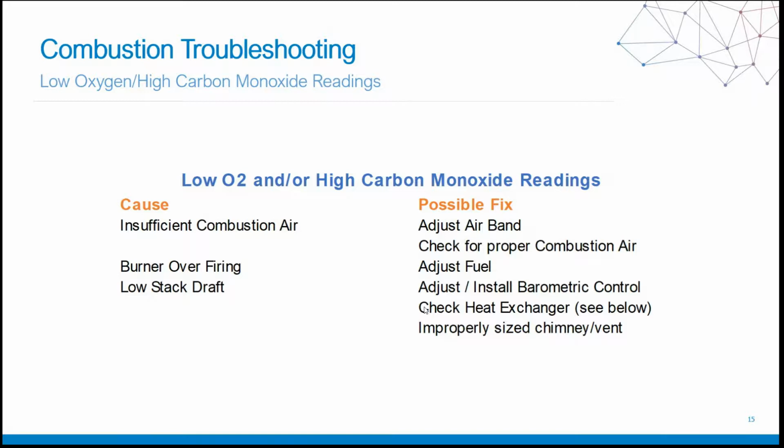Burner overfiring. Do we have to adjust the fuel? Do we have to check that? We have to make sure we have a proper fuel adjustment with the system. Do we need to back down the gas pressure? Do we need to increase the gas pressure?